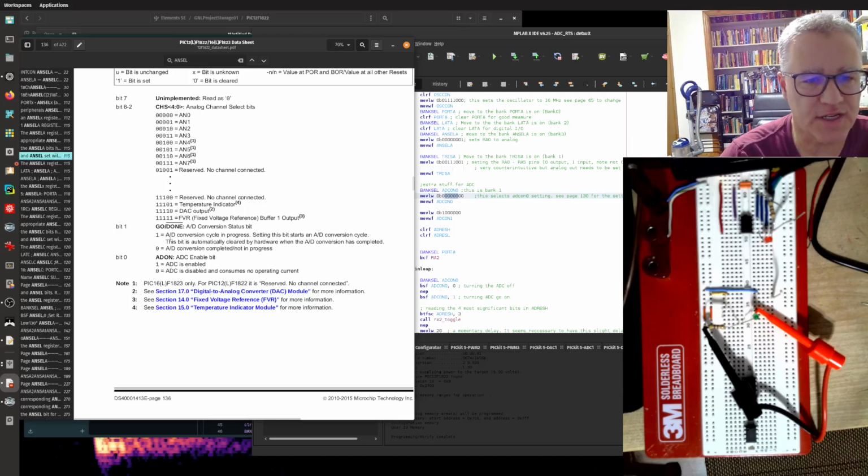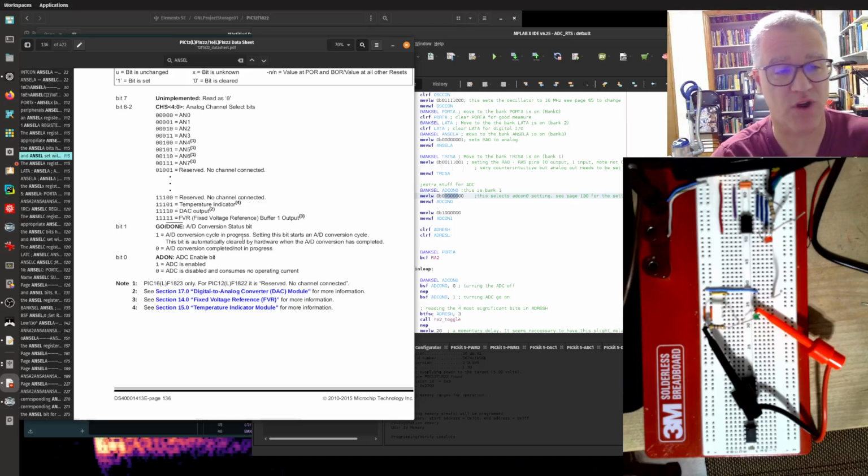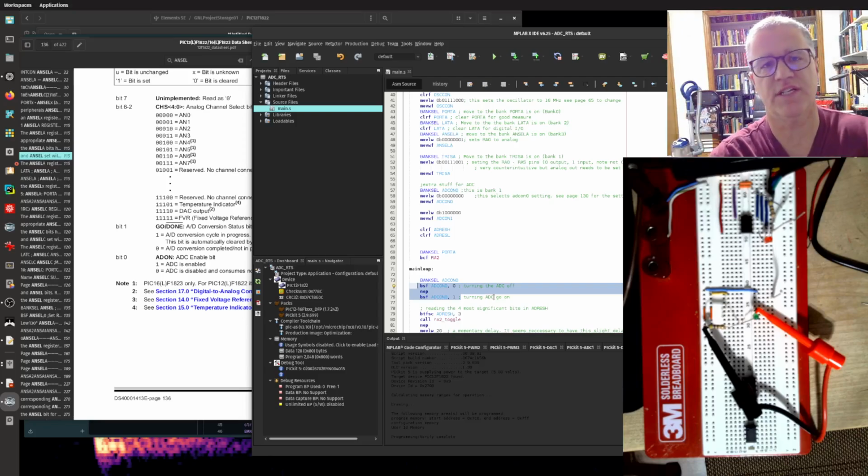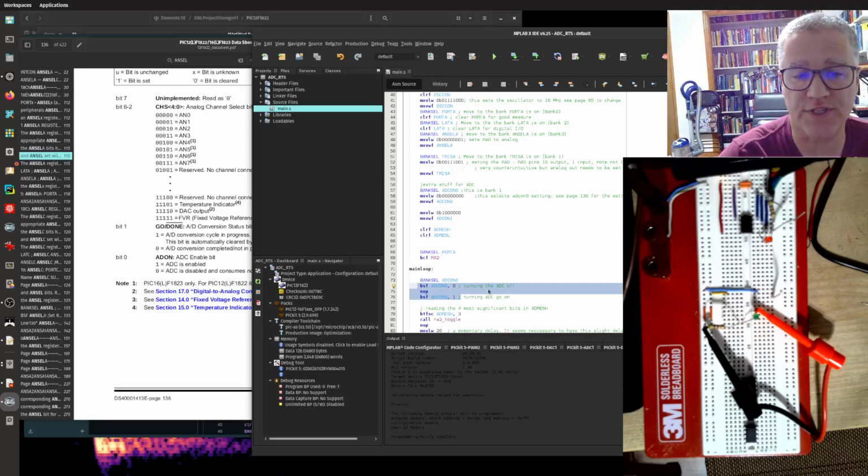This is actually what starts and stops the reading of the analog to digital conversion process from the peripheral. So we set that to 0 to begin with. Then I'm going to just jump you down here quickly. This in the main loop is just turning on and off the analog to digital go. So when it's on, it'll start to read a digital. When it fills the register, then it will automatically go forward. So it's actually quite easy to work with, and a lot is happening kind of automatically on the microcontroller.